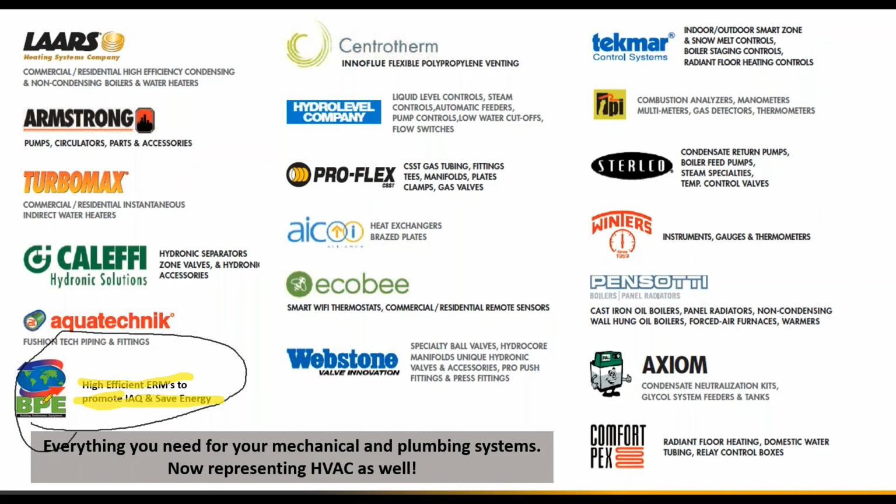When you're bringing in a lot of makeup air into the building, it could be as low as 20, 10, 0 degrees. It could be below 0, right? So if we can make sure that we're preheating that, utilizing an energy recovery ventilator, or energy recovery module, again, that's something you could reach out to us about, and we can help you size up for your building and application.